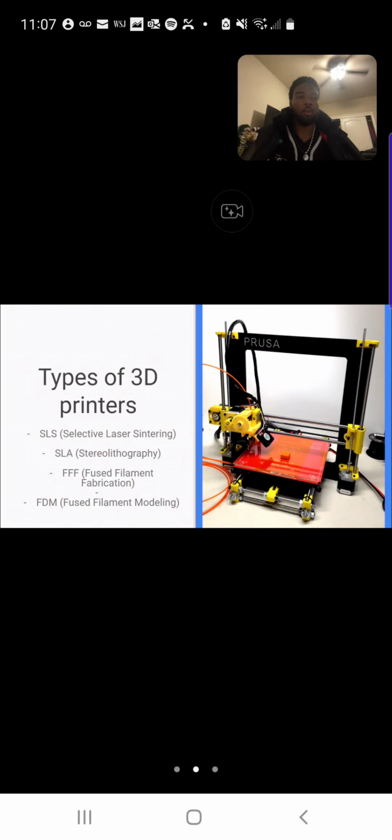And how the process works is basically, just like how my partner said, when you have a 3D printer, at least when it comes to these SLS and SLA printers, at the bottom you will either have a resin or a powder surface, and at the top, you will have the laser, and then that laser will be pointing its UV light towards a mirror, which will reflect that light down to the surface, which is the resin or powder surface.